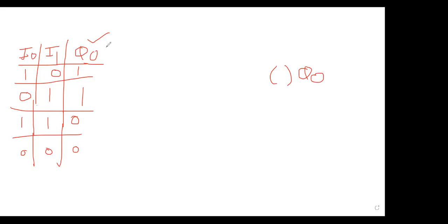What does it mean? In some examples, you can have many outputs, correct? Q0, Q1, Q2, Q3, many. So when you make a program, don't be worried about all outputs. You start from the first output, finish it, then you think about the second output. Don't mix. So again, make a truth table, go to the first output, take a coil for it. After taking the coil, you think that output is not for the others. Check the true condition of that output and add the status of all inputs you have used.